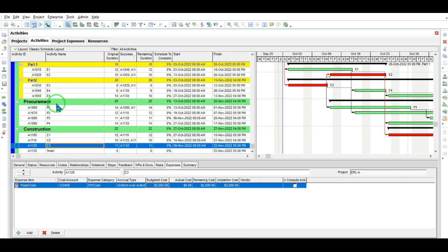Therefore, I want to use this situation to teach you the global change in Primavera software, which enables you to have powerful flexibility in terms of defining different things. First of all, imagine that I want to have a column which is the location ID, and if it is 1, it's the representative of location B.